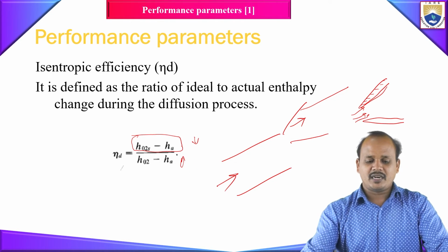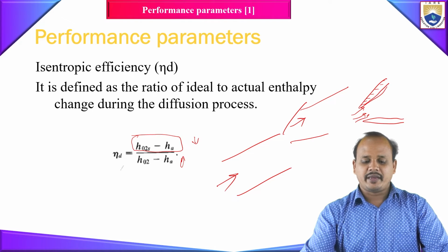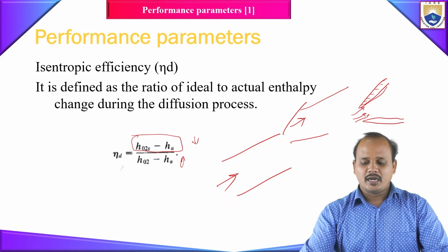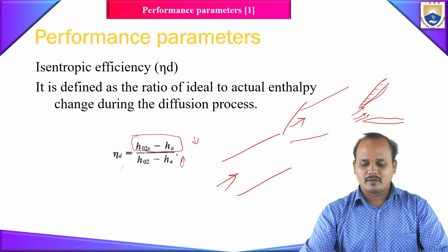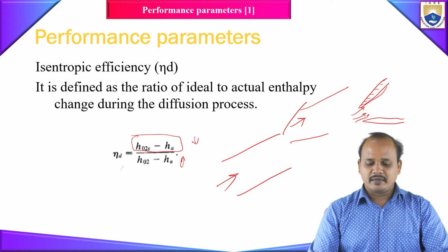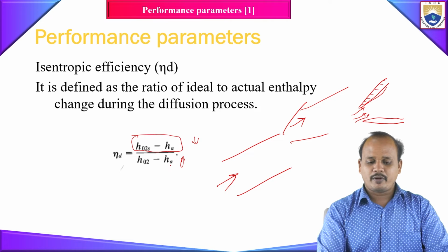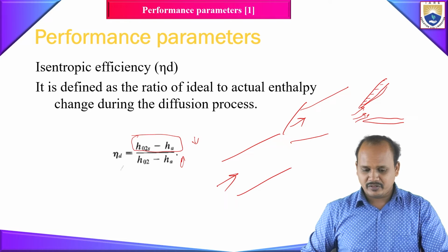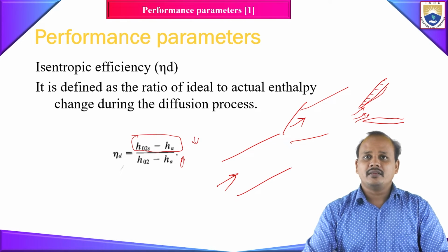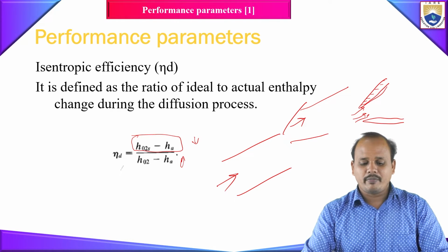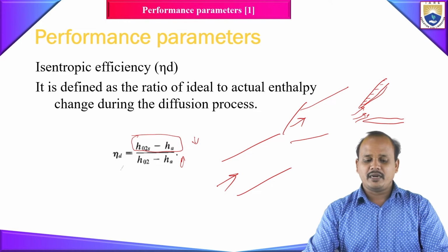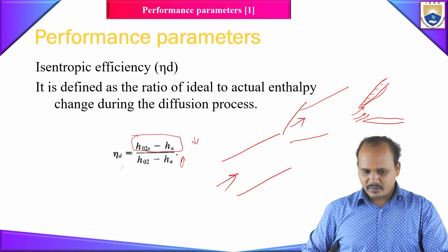Okay. So another name you can use for this isentropic efficiency is adiabatic efficiency. If the process is not isentropic, there is a process with loss, which is basically an adiabatic process, right? So here you can say either isentropic efficiency or adiabatic efficiency. For any intake, this isentropic efficiency or adiabatic efficiency should be close to 1 or 100%. That is, the ratio should be close to 1 or 100%. You won't get 100%, but we should try to get closer to 1.